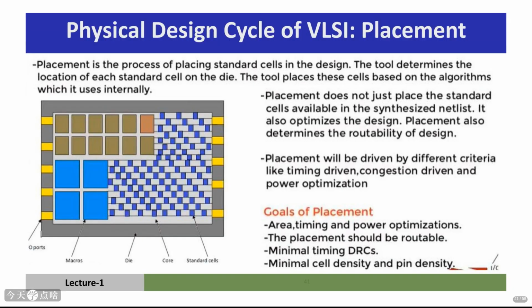In the context of standard cell design, placement refers to placing the pre-designed standard cells onto the chip. The CAD tool uses algorithms to determine the optimal location for each cell. It's not just about placing them, it's also about optimizing the design for area, timing, and power, and ensuring the design is routable.